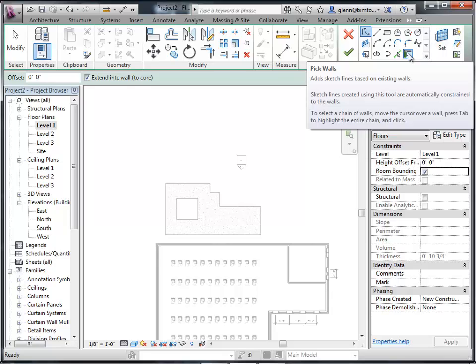So this should almost always be checked. This is almost always a good choice. You have the choice here about whether it should go to the outside of the core or to the inside of the core. This is the issue of, if you have platform framing where you have the floor inserted with the studs above and below, it goes to the outside core. If you're going to hang on a ledger on the inside, then you can go to the inside as you place the floor. But it almost always goes to the structural core. It rarely goes to the surface.